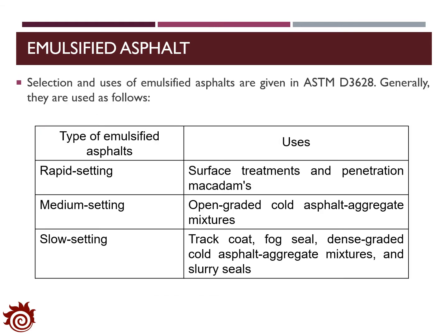The table here summarizes the cases of using emulsion with different settings. Basically, for surface treatments and penetration macadam, we have to consider rapid setting emulsion. For open-graded cold asphalt aggregate mixture, we need to consider medium setting. For tack coat, fog seal, dense-graded cold asphalt aggregate mixture, and slurry seals, we need to consider slow setting.